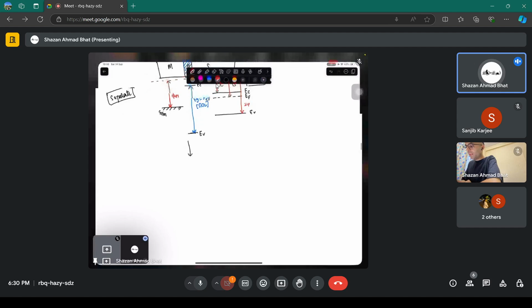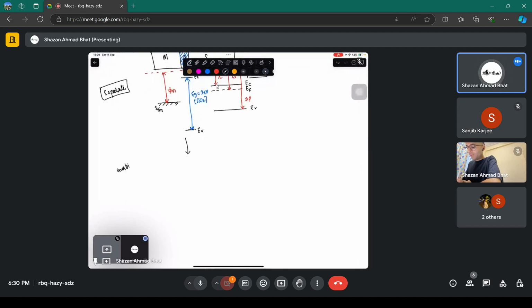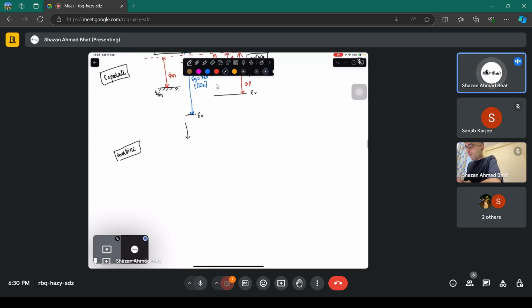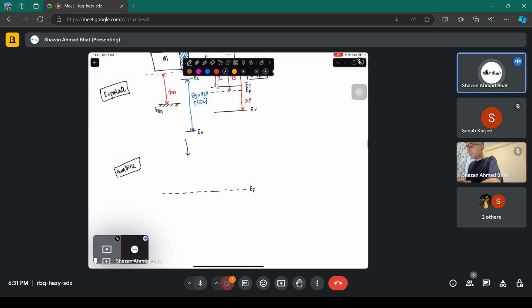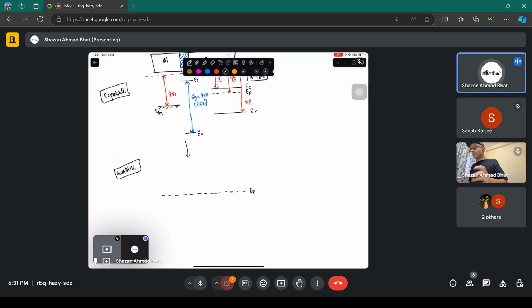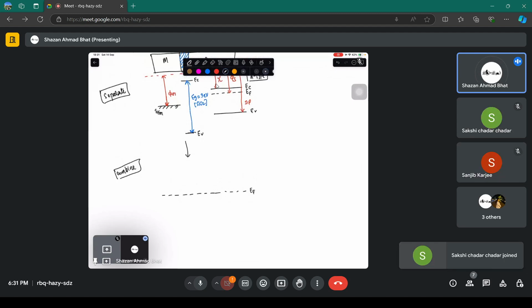So when you combine these particular semiconducting systems, you know from the basics that you should have a common Fermi level in the system, because this is going to behave as a single system now. If the Fermi level is going to be common, that means there has to be some band bending somewhere else in the system, or maybe that may be compensated by something else.